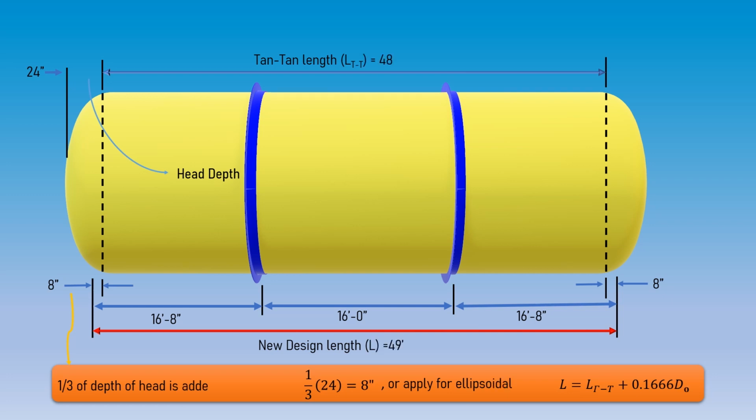Let us go back to the ongoing design problem, as the selected thickness is insufficient for the shell. So choosing option 2 and adding stiffening rings to the vessel, angle type stiffening rings are being added. These stiffening rings divide the vessel into three sections at relative positions. Now each of these three sections will be treated separately and evaluated for the external design pressure.